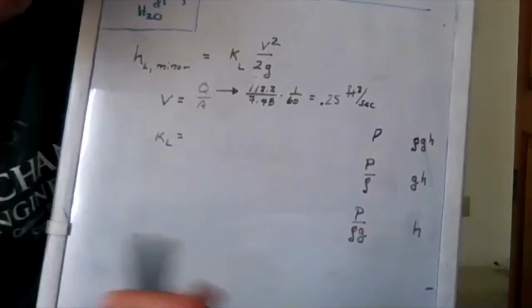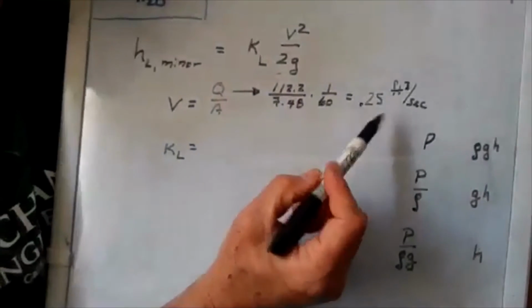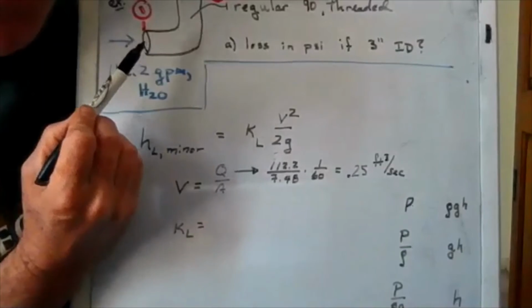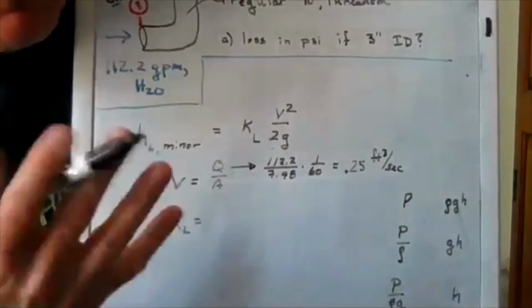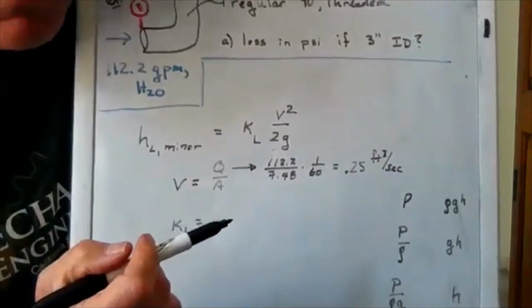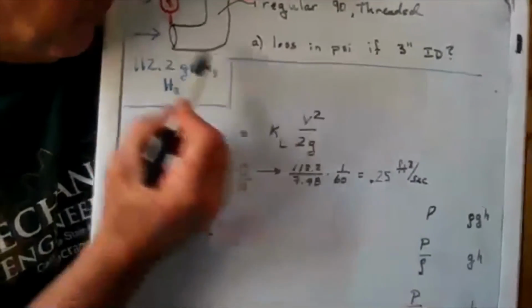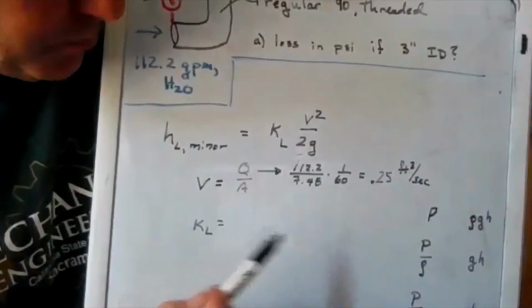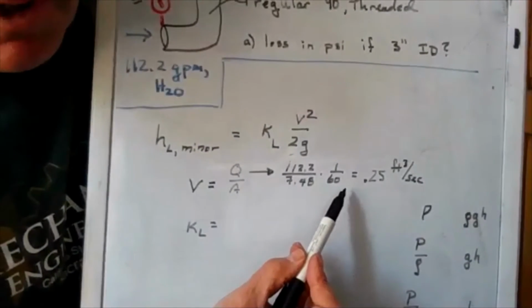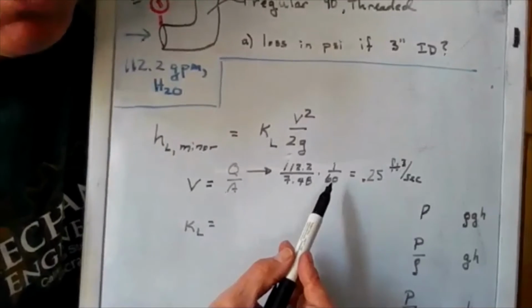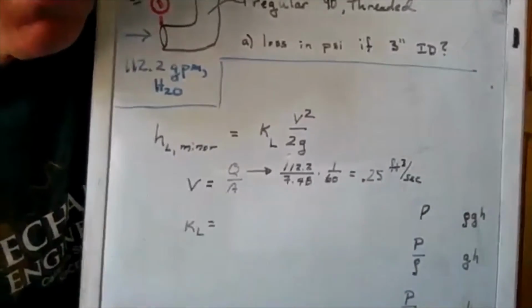So if you haven't done so already, keep going and figure out as much of that as you can on your own. All right, intermediate step, I got 0.25 cubic feet per second for the flow entering that opening. That may seem small, but remember, a cubic foot is a substantial amount. And if you counted a second, 1/1000 cubic feet went in there, wow, that would be really moving. That's a preliminary step, and then we're going to use that to get the average speed of the water entering the fitting.